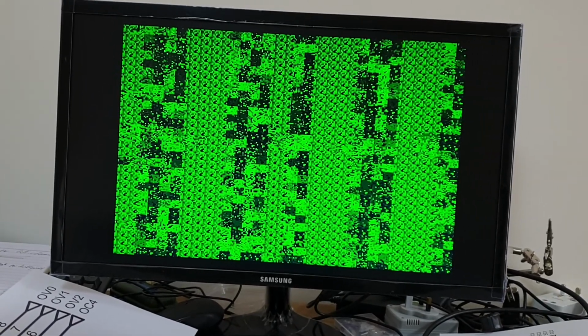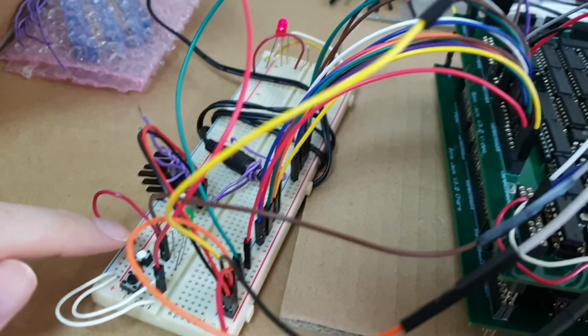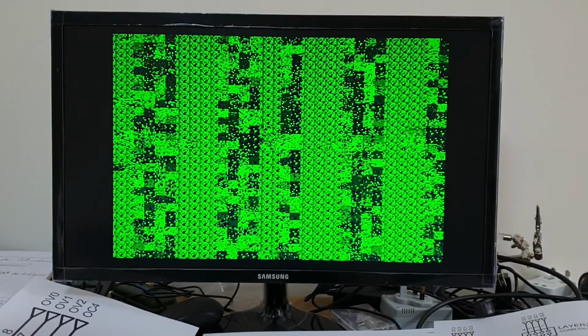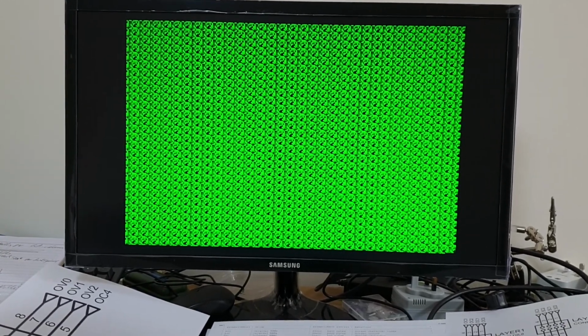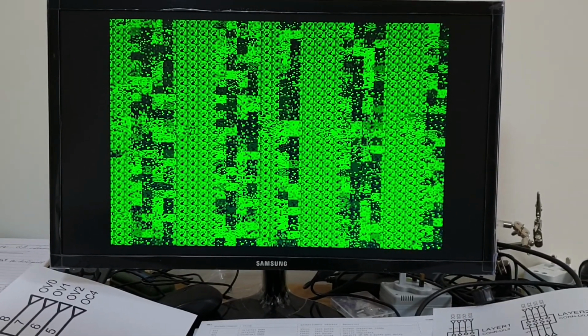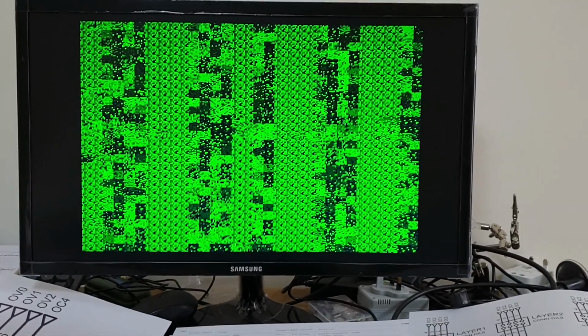If I press this button here, currently at the moment it's low, but if I press it now, it goes high on the extended memory bus. And what that means is that the internal chip logic, when the screen does this, means that there's contention, and it's actually outputting probably character FF or 3FF, because all of the lines are in contention, therefore it reads as high.